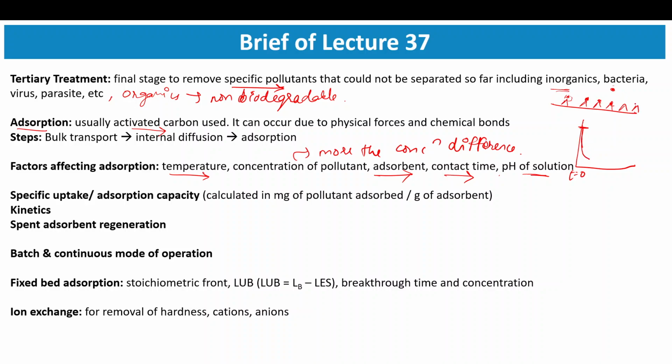After a certain point, the rate reduces, and there will be a point where no vacant site will be available. At that point, you can say this adsorbent has saturated. So this point is known as saturation of the adsorbent. So yeah, contact time is an important factor.